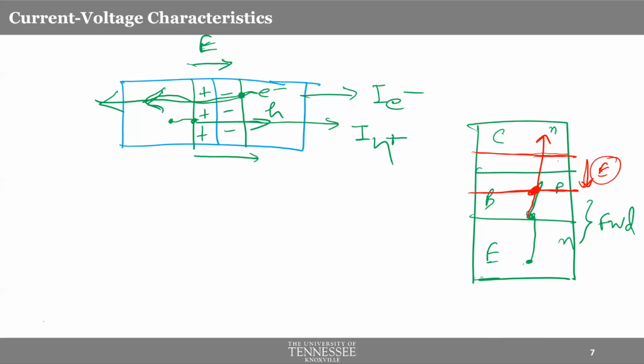So imagine, ask yourself this question: mind the notation, current flow from emitter to collector. Whether it will be good for our current flow from emitter to collector if the reverse biased region width increases. That means you have stronger reverse bias. Will that be beneficial or not? Here is the answer.